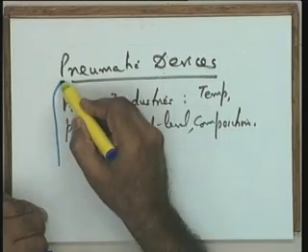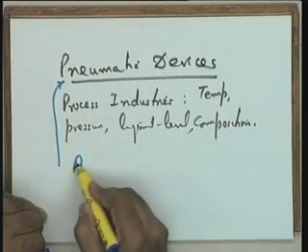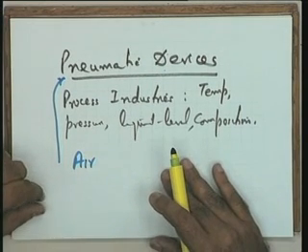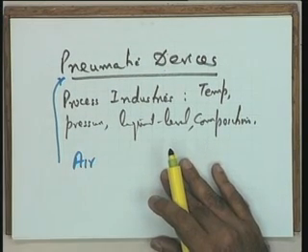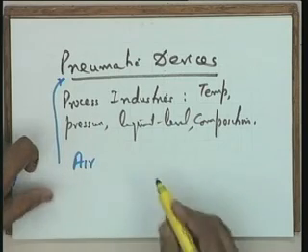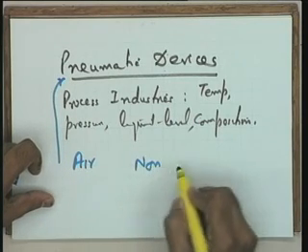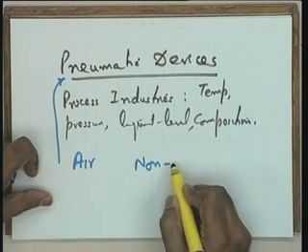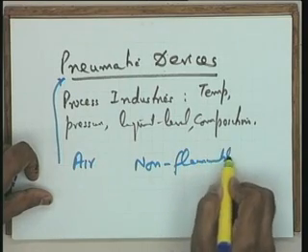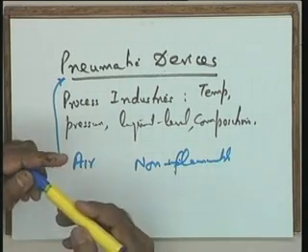You see, one of the primary reasons is the simplicity. Well, air can be exhausted to the atmosphere, you do not need the reservoirs. Okay, it is available in abundance, no problem of hydraulic fluid as you require in hydraulic devices. What else? What could be the other advantages? Probably non-inflammable is also one of the important advantages of the system. What else, please?